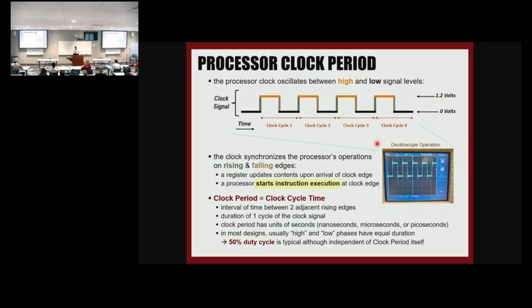And then if you really measure, if you have a clock generator on a circuit, and if you use an oscilloscope to see how it looks, it's never perfect. It looks like this, right? You can see some small fluctuations there. And for that reason, usually when we define a 0 and 1 in digital logic, we say anything more than 1 volt, for example, is 1, and anything less than 0.2 volt is 0. Because we want to give it some space to make those fluctuations, and we don't switch from 0 to 1. This is a clock, right?